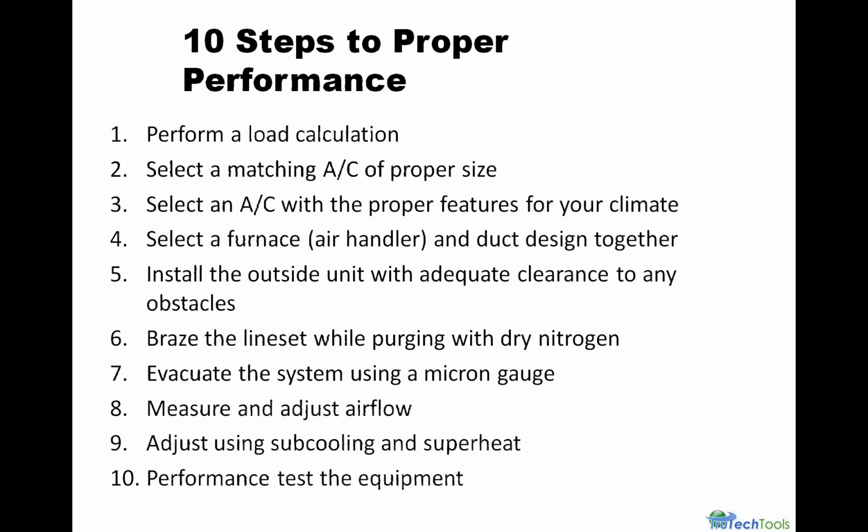There are 10 steps to proper performance, and you need to make sure that you don't skip any of them, because we're talking about making the thing work correctly. There are some things we have to do in the front end because this is a field installed unit, so it's going to require a field installation and a field commissioning procedure. But we want to make sure we perform a load calculation so the equipment's the right size.